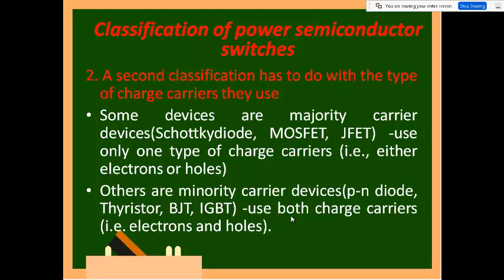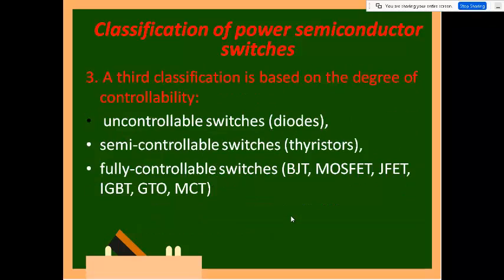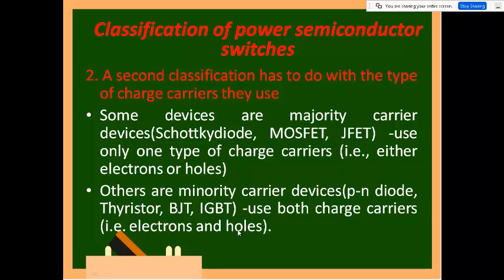But there is always a problem with these minority charge carriers, because they cannot be turned off. You can only turn on, and turn off is not possible. The minority itself is able to conduct the device, and when the device gets turned on, automatically the N regions on both sides will supply electrons to this P, so you lose the control. Control has gone to the external power, as we have seen in number 1, not from your side. So that is the minority problem.